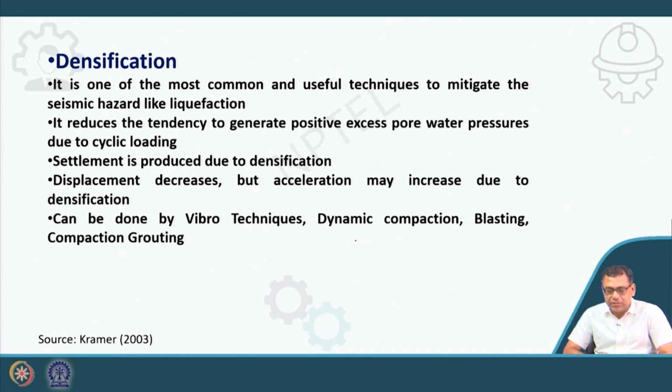Settlement is produced due to densification. So, remember that because of the densification, settlement will occur on the surface. Now, displacement decreases, but acceleration may increase due to densification. One more thing: we will reduce the displacement, but as the density increases, the acceleration may increase. Okay. That can be done by vibro technique, dynamic compaction, blasting and compaction grouting.